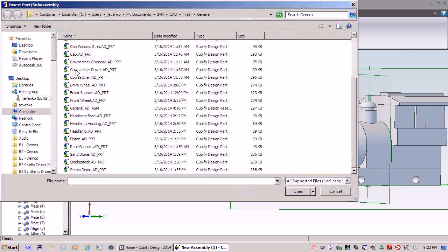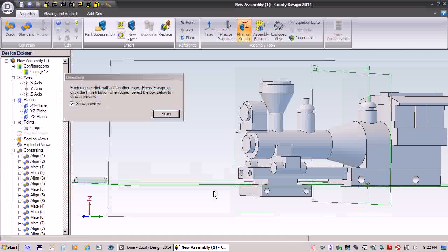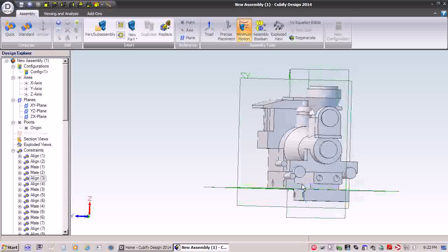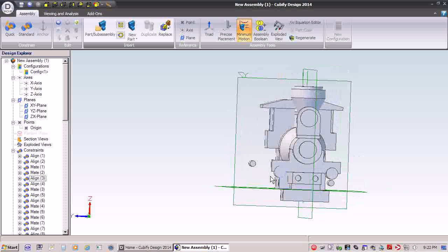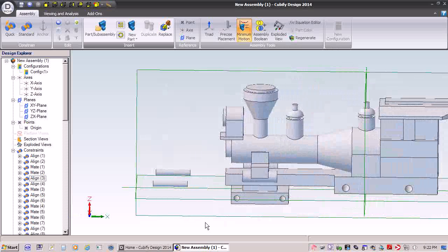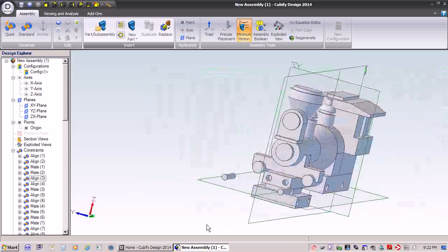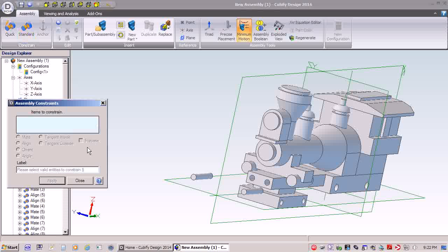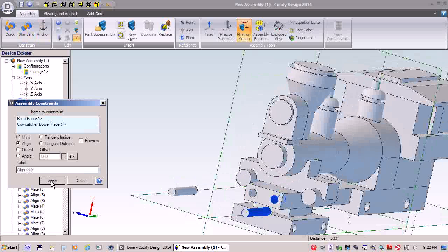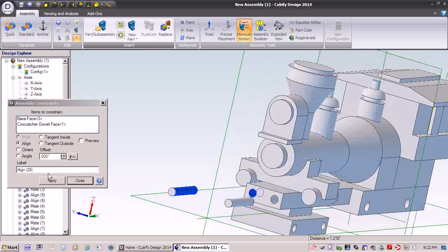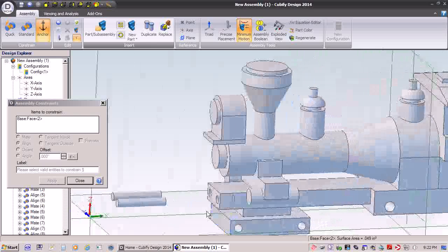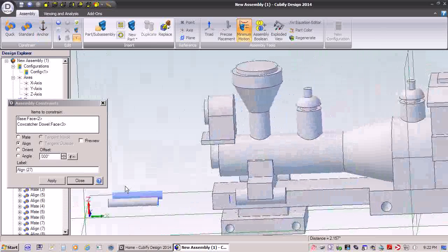And so this is a Cowcatcher. The Cowcatcher is attached with these two dowels. So let me create two instances of this dowel. And let me get them roughly in place. Make sure they're not behind where I'm trying to attach them, so they don't hide any geometry. Alright, cylinder to cylinder, so that requires an align. And doing the mate to bring them into position with each other.